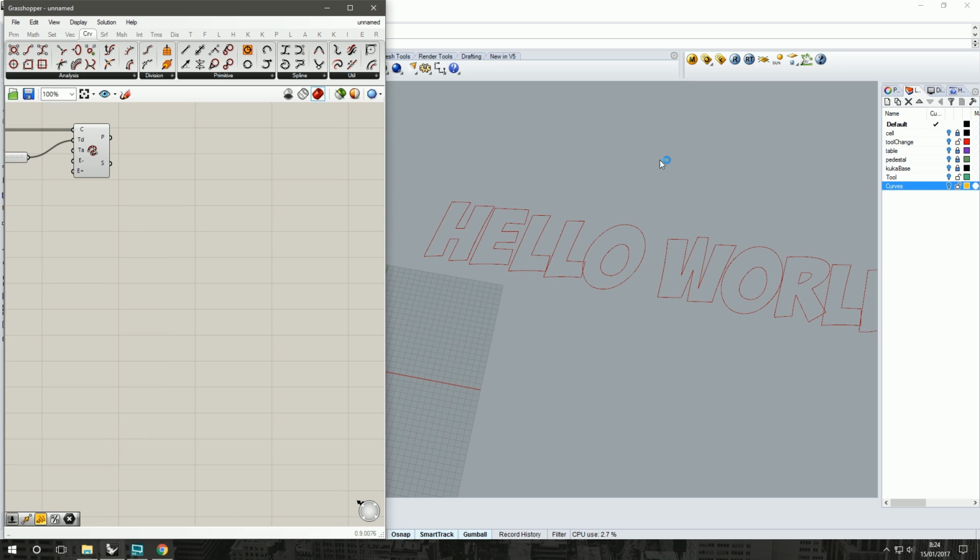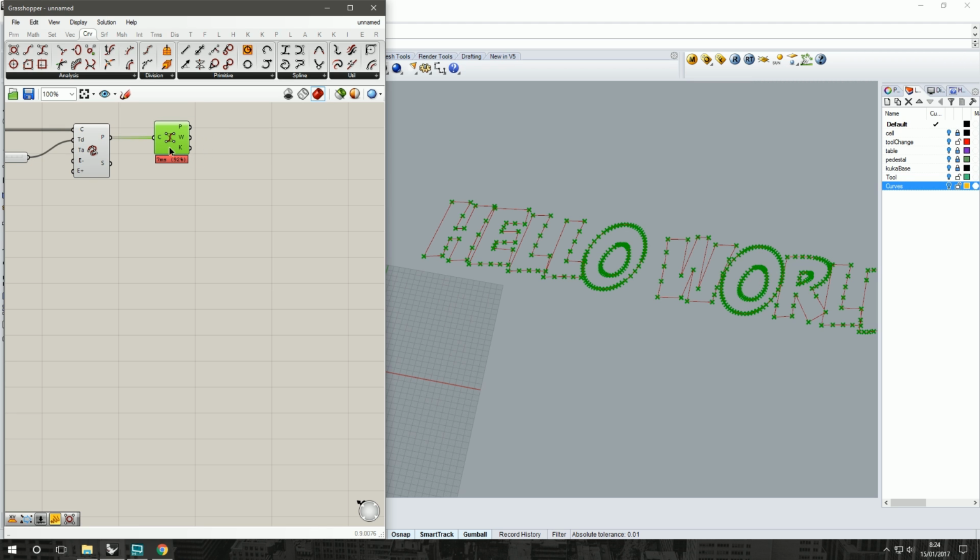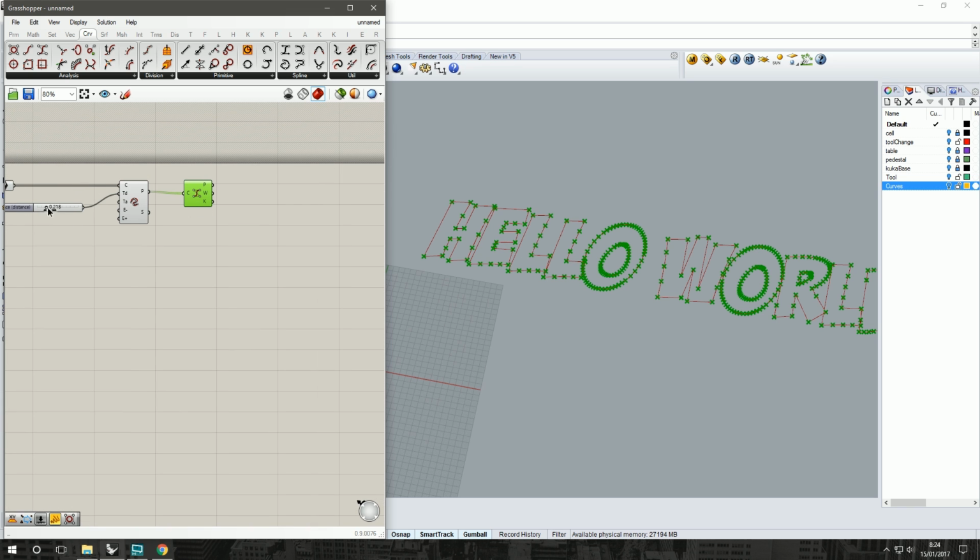Now we need to set up a series of control points so that we are basically telling the robot where to move on these lines, which is under Curve Analysis, Control Points. We will take our polyline, put it into our curve, and that gives us a series of control points on those polylines that we've created. So if we can show what happens when we increase the tolerance. Basically that's saying the distance we're willing to move away from the original curve. Around there should be fine. We've got a nice, beautiful curve on our round areas. And on the straight, we don't need any points where it's just a straight line, which is perfect.